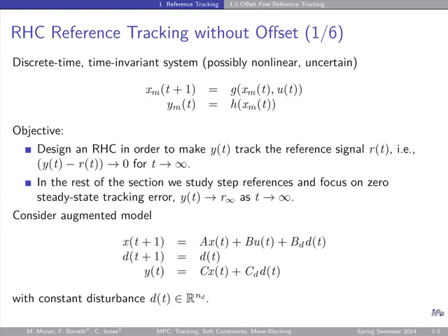If this is the case, then the observer steady state, with constant input obviously, is going to converge to some steady state. So this observer steady state is the X steady state and D steady state, X infinity and D infinity. That's what this is converging to. And obviously I have some U, which is constant, this U infinity here. So if everything is constant, it will converge to a steady state defined by this linear equation here.